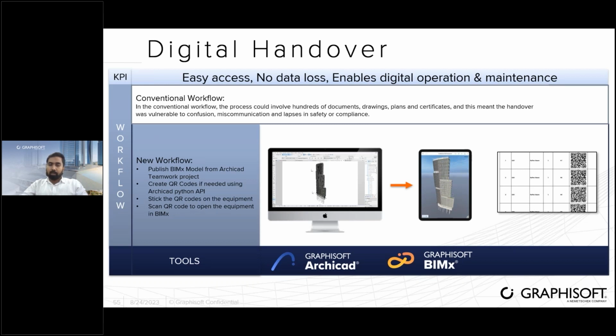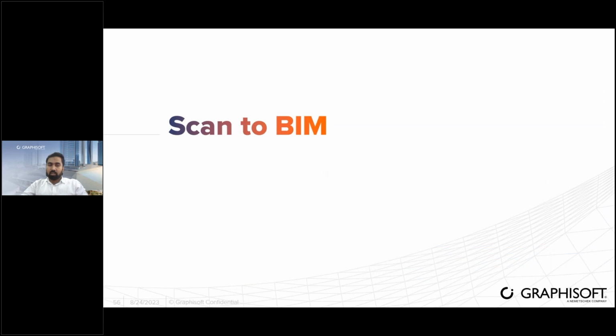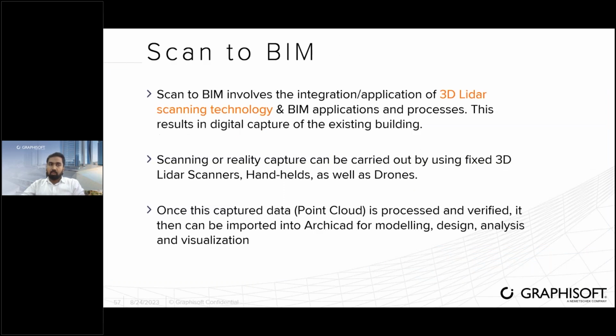Okay, so let's move on to the next topic, which is scan to BIM. As per this workflow, we can use the 3D LiDAR scanners, and then we will be able to get the point cloud information, which sometimes needs some post processing.